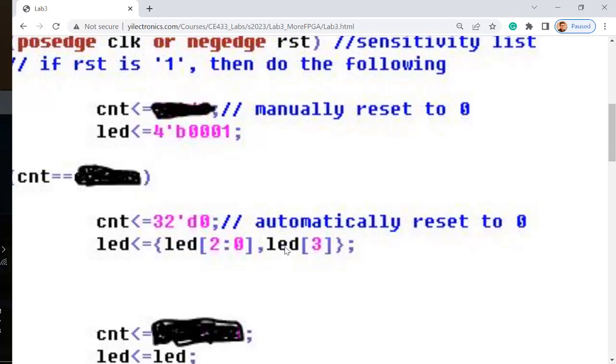In that way, you can shift this. What's actually happening is you're shifting this bit to the left. Makes sense? Recombine them. The curly bracket will do that job. And then after you recombine them, change the order and assign it back to LED. So after that operation, you're getting 0010. So the second LED will be turned on.